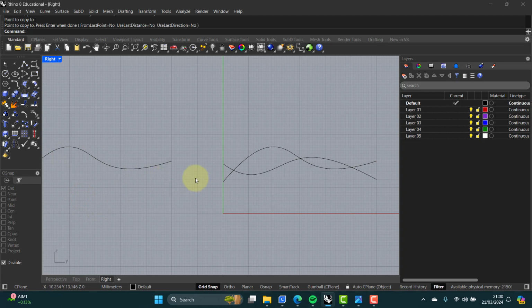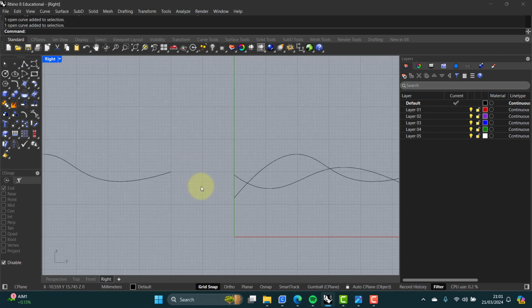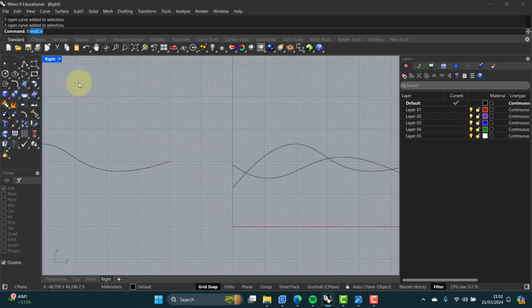And I'm going to show you how this curve can be joined to this one. That one's not quite so difficult to envisage. That just looks like you would fillet that with an arc. That would work okay. But from here to here is a different story. How do you get from one to the other? Obviously there's a straight line, but if we do a curve coming out here, it's got to somehow curve back into this one. And this is where the software really does start to excel. So we're going to use a command called blend, BlendCrv, blend curve.